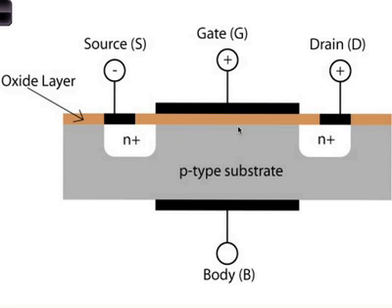Now to do amplification, we know that the gate voltage relates to the channel conductivity non-linearly because of the depletion width. Okay? We model that. Look at that very quickly. Any signal you apply to the gate translates to the current with some amplification.